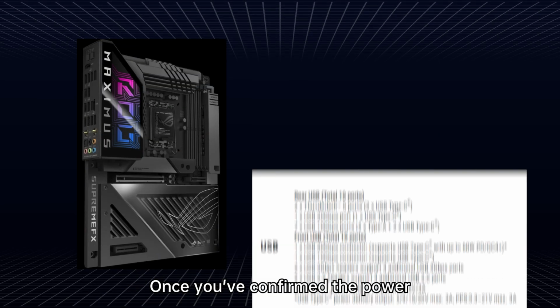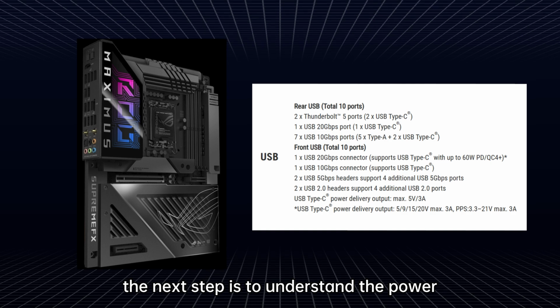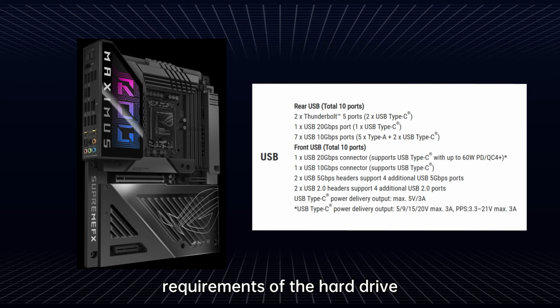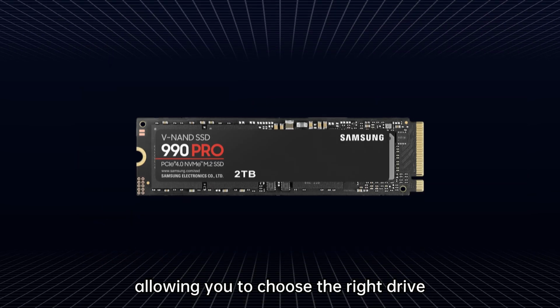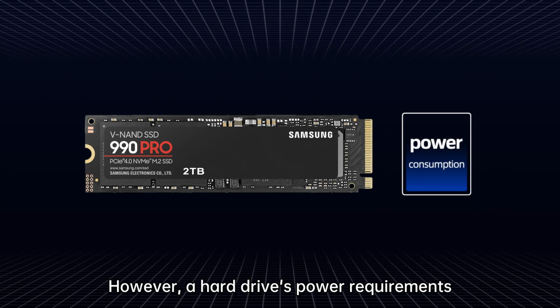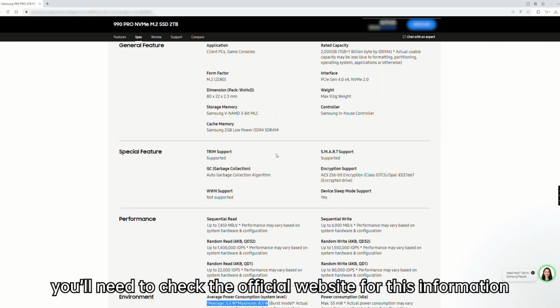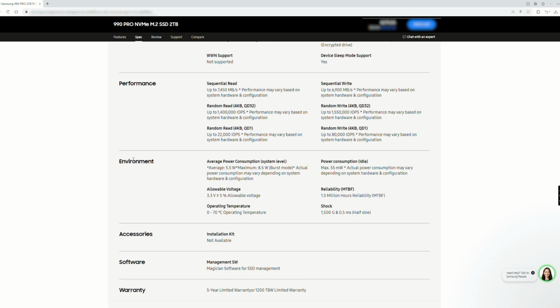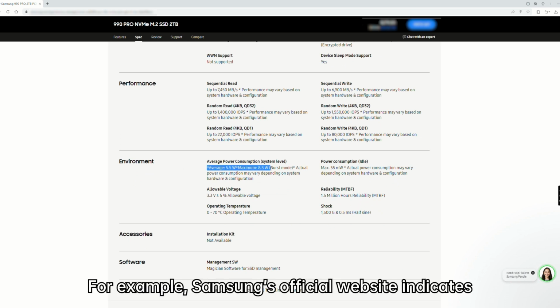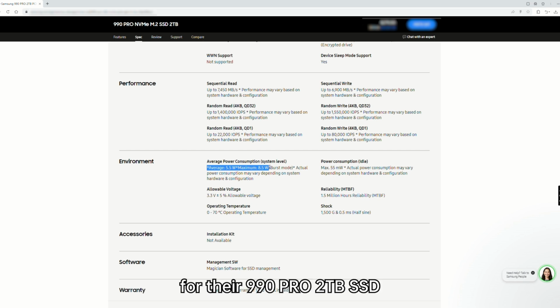Once you've confirmed the power output specifications of your computer's interface, the next step is to understand the power requirements of the hard drive, allowing you to choose the right drive and external enclosure. However, a hard drive's power requirements aren't labeled directly on the drive itself. You'll need to check the official website for this information. For example, Samsung's official website indicates that the maximum power consumption for their 990 Pro 2TB SSD can reach up to 8.5 watts.